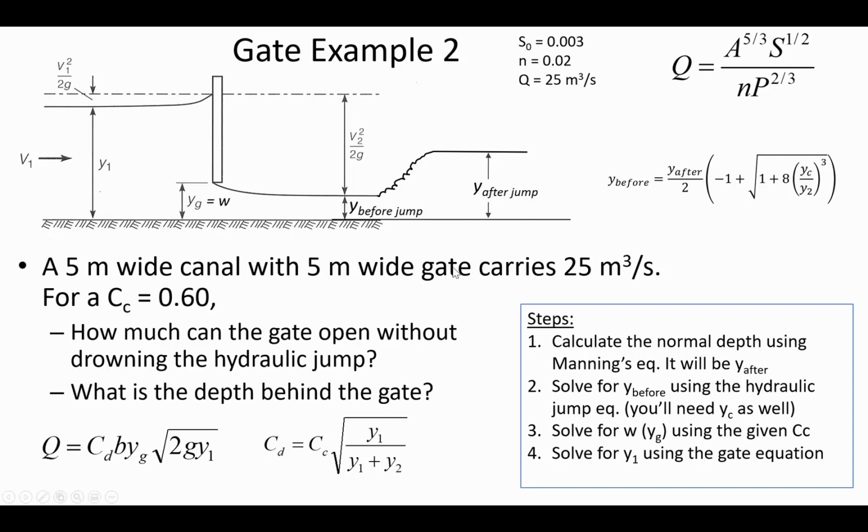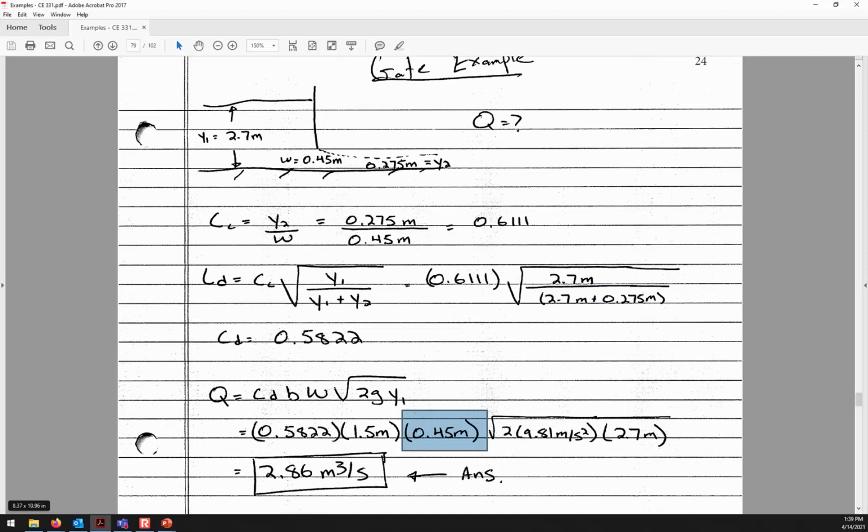All right, so starting downstream, I'm going to pause for a second and calculate the normal depth here. So we're solving for the unknown y with Manning's equation. Let's jump ahead. I'll show you the normal depth and then I'll turn you loose to work independently from that.